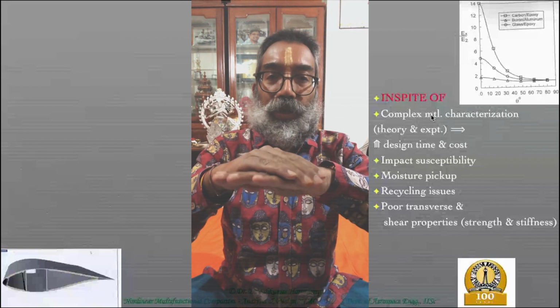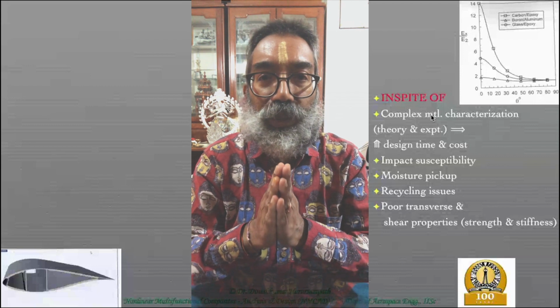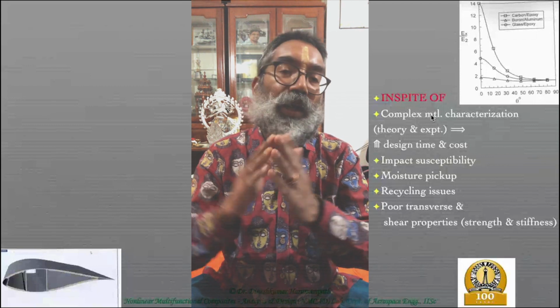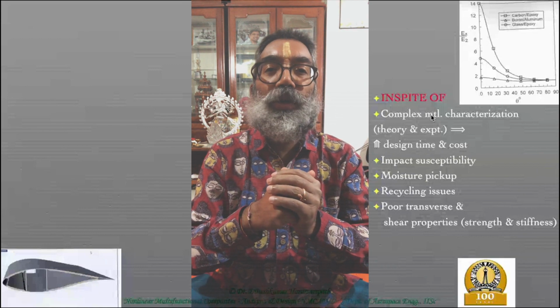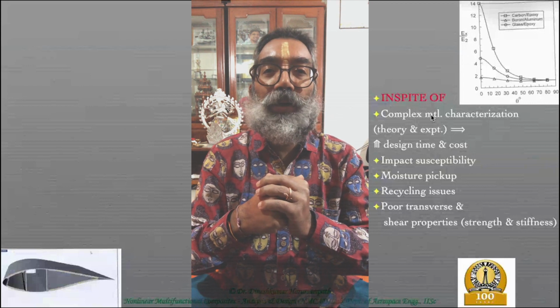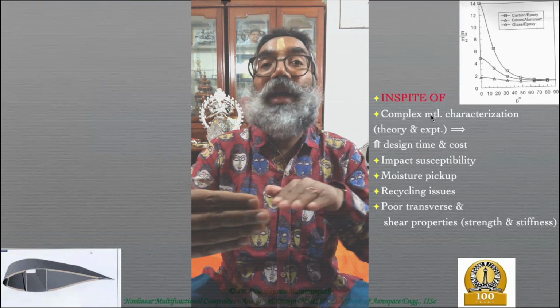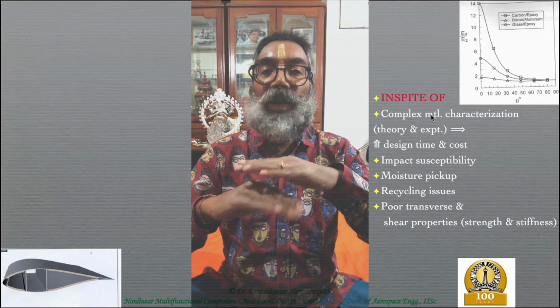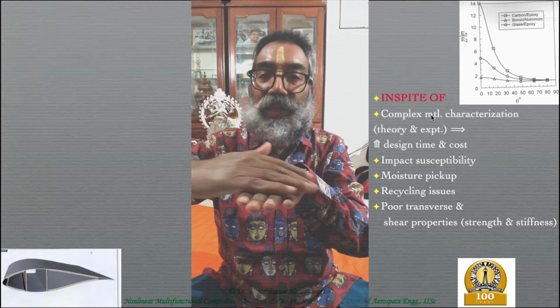We saw in terms of the stress transformation, when we discussed it in a previous class, that under torsion or pure shear, it can be thought of as a pure compression in one direction and a pure tension in a perpendicular direction. Now if you put the fibers in those directions, you can actually handle transverse shear. So one way of handling transverse shear is to have, apart from 0 degree fibers, 90 degree fibers.